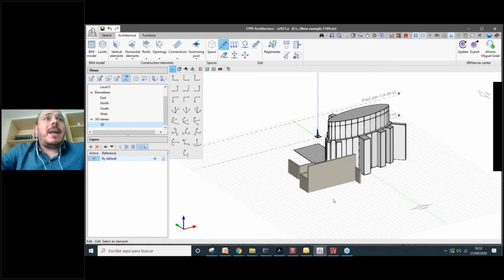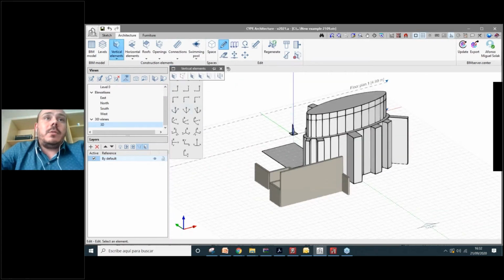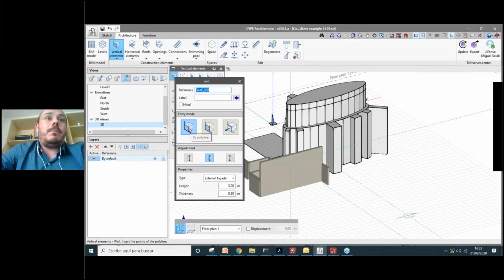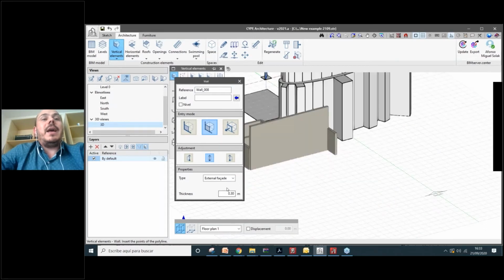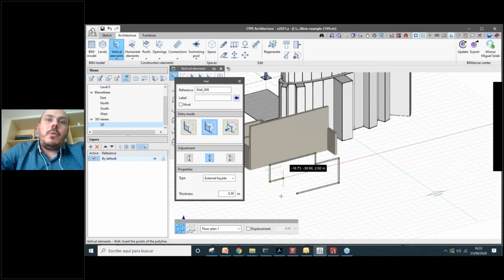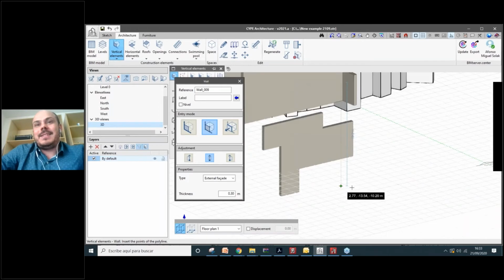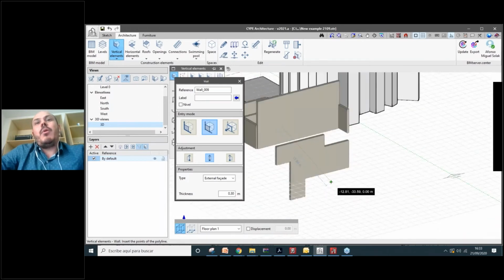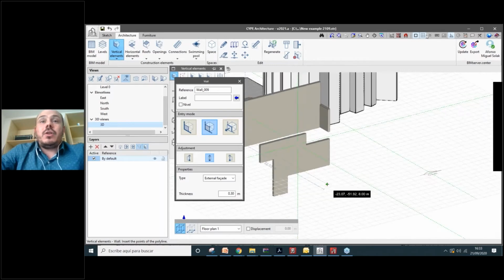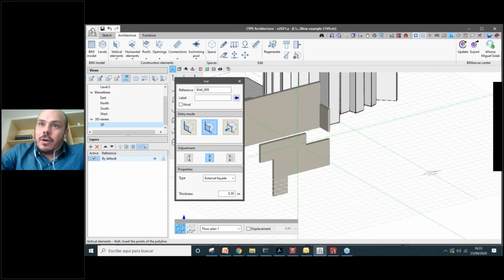Okay, but there are other ways to introduce this wall. The first one was this polygonal by polyline, for example, but we can create by points. In this case, we don't have the parameter height. Why? Because we will create one point, another point, another point, another point. We can create the geometry that is free of height. Let's say that you can create, adopting different points, the geometry of your building. It was orthogonal, but could be not orthogonal, like this, for example. Could be orthogonal here, but now it's not orthogonal.